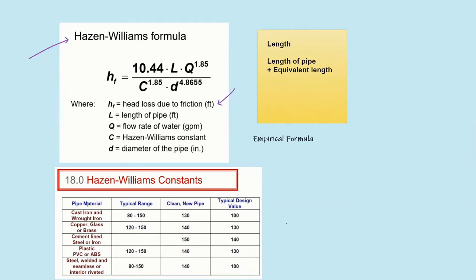But for our calculations for dynamic head, you need to understand your head loss due to friction and the static head value, which is the difference between the elevation of the source and the discharge.